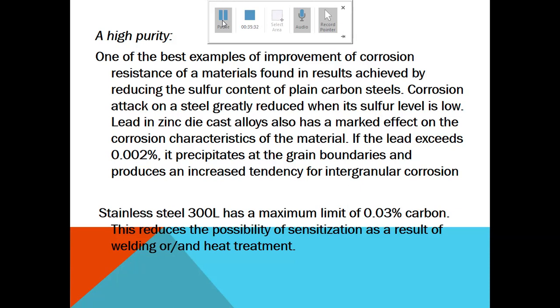Cellular dislocation morphology is less susceptible to environments that cause corrosion. Dislocation arrays, stacking faults and other lattice defects in the microstructure are regions of localized attack and can be sites for crack nucleation in the corrosion process.